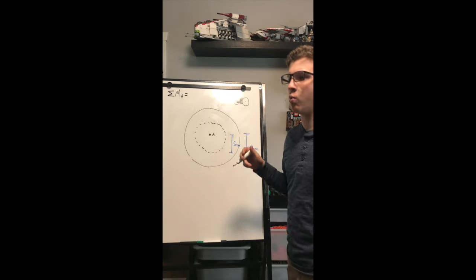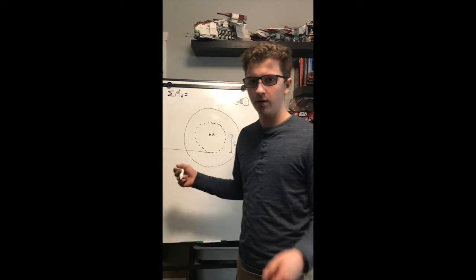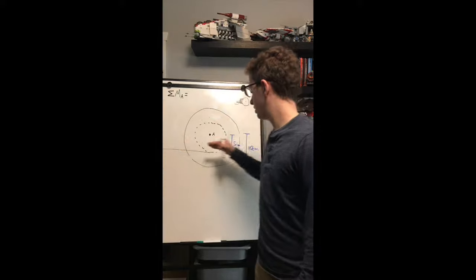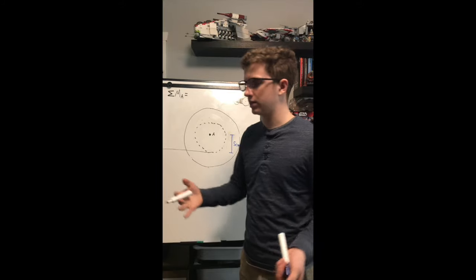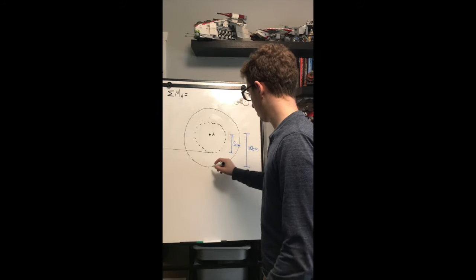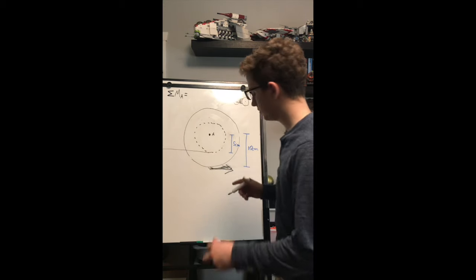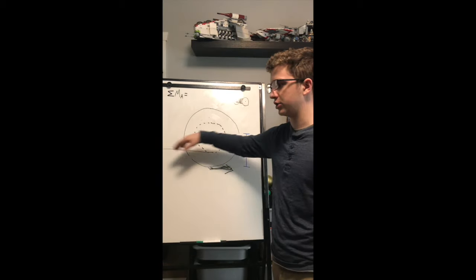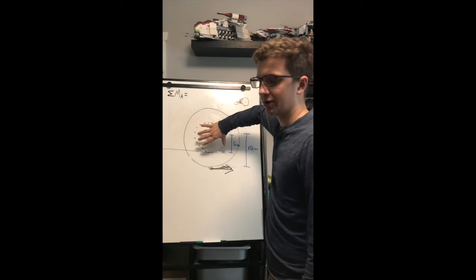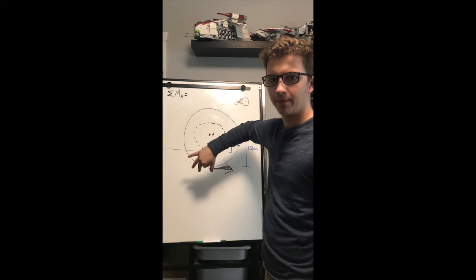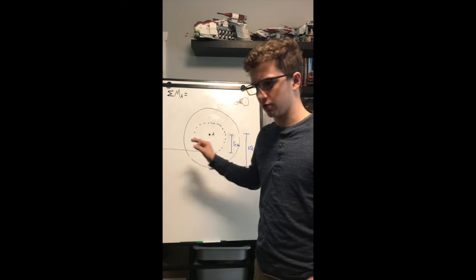So if we were to take a wire that was attached to this spool, let's say it comes off at this point here, and we're going to say apply a force tension to that wire. Now, obviously there's going to be a force friction resisting the whole thing to just start sliding backward, and that's going to be in this direction here. So now we have two forces, the force tension and the force friction. And you can obviously see that this is either going to roll forward or roll backward. But it's obviously not going to just slide forward or slide backward, it's going to roll.